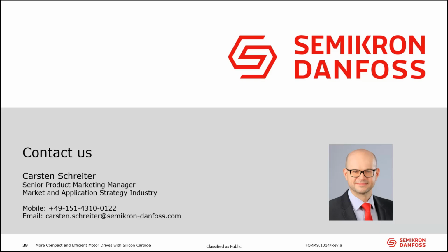Okay. I have a question here: if we're replacing an IGBT power module with a silicon carbide power module, it may not be just a simple plug and play replacement. Are there any considerations that need to be taken for changing from IGBT to SiC MOSFET? Of course, it's not a simple plug and play. There's some things, of course: the gate voltage is different, right? I mentioned for the chips we use, you have 0 to 18. If you have an IGBT that switches -5 to +15 or something, then obviously you have to adjust your gate voltages a little. The gate resistance will also be different.